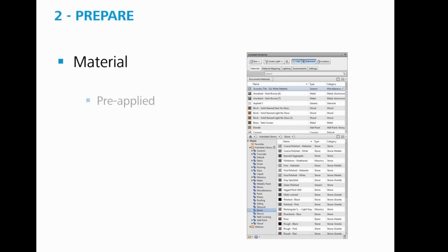So now there's an important tip to bear in mind. And that is there's some settings inside of Navisworks that you should switch on, or the mode you should change to, so you actually get a good feel for what the end result will look like. And that means to switch on the full lights, because otherwise it uses some headlights or some simulated scenario. But the cloud rendering uses the full set of lights. You should switch on the full lights so you actually get the same lighting appearance.